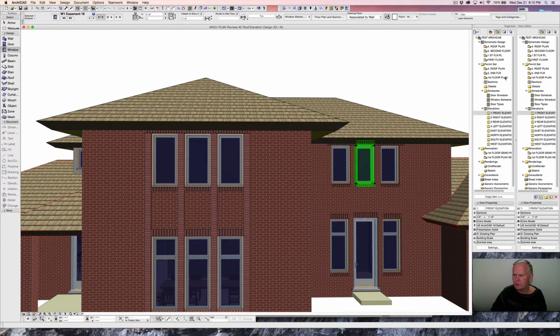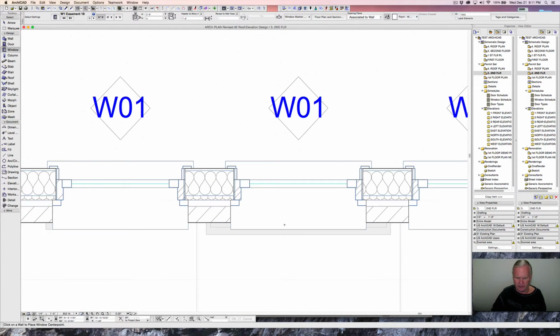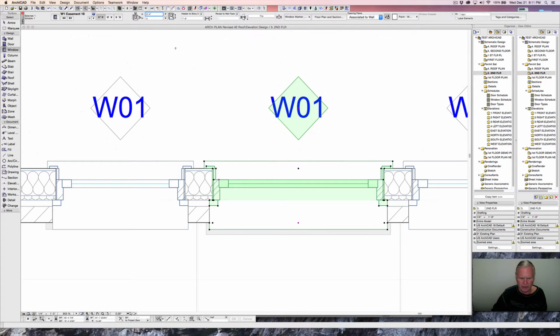And if we go to the second floor and look at that, and look at the window down below, this is currently set using the center anchor point. So if we increase its size here, it's currently 2'6", and I think that's a 3-foot door plus 2 inches. That's 3'4". So we're going to change this up here to 3'4", and it should line up with